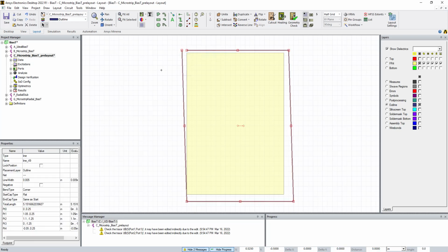So now I've just kind of randomly drew this line. It has a width to it. So we go to our properties. First thing you do is make it a zero width line. Bam. Now this is done and it defines multiple points because these are segments of lines. So we have to type in each line segment. We're going to do it parametrically.